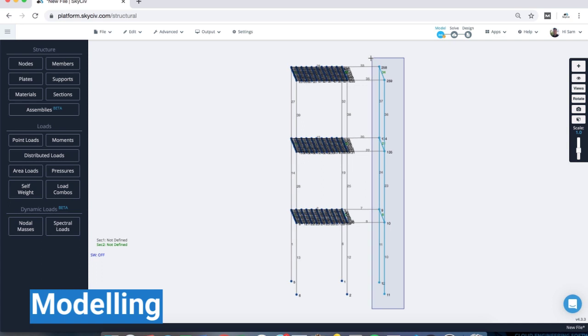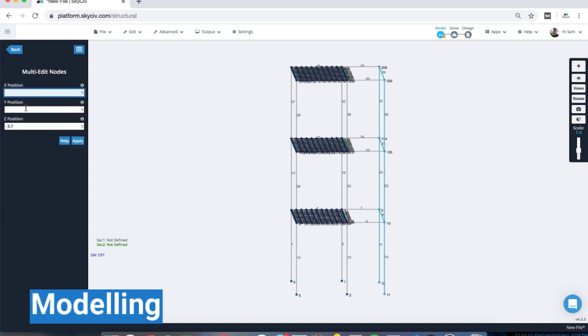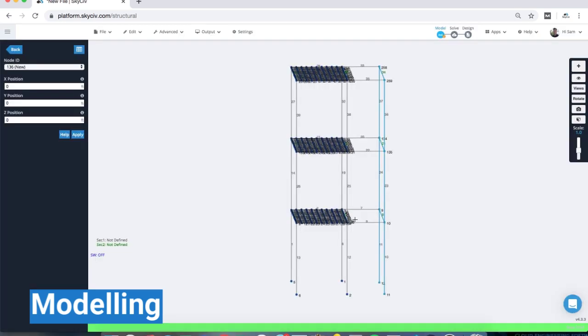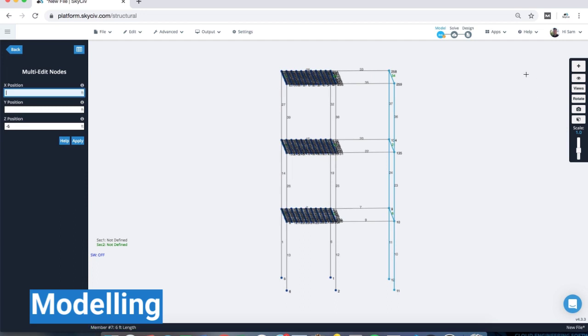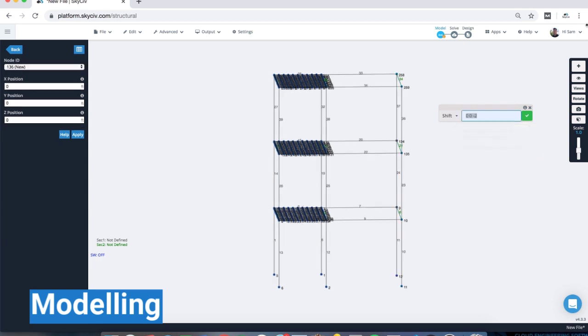So if I want to move that right wall, I can use that selection tool, and then I can either go to nodes to then move the Z position to say something like -6. I'll confirm that, which will open it up. Or I can also use the relative tool member where I hit R, and I can just shift my nodes by some XYZ component. So 0, 0, 0, -2 in the Z, something like that.